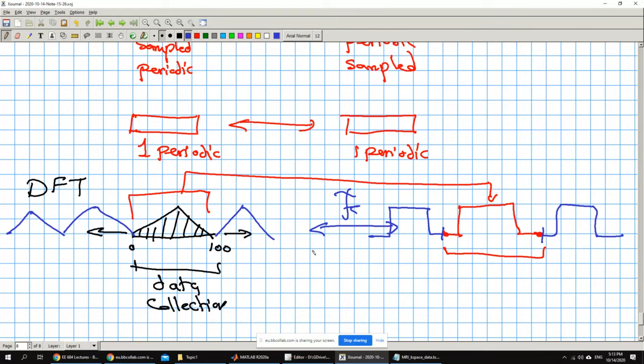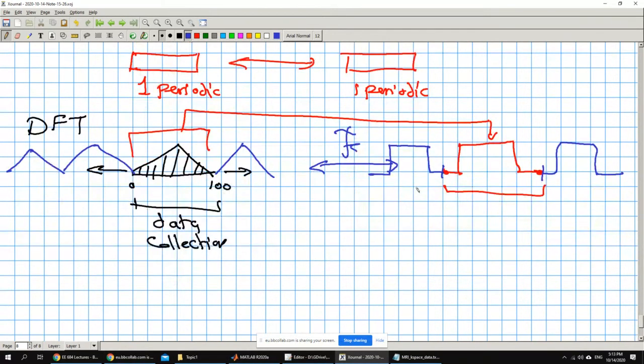If I compute the Fourier transformation of any signal, you will see only one period of the signal in time, and what comes out in the frequency domain will be another period of the frequency domain of this particular function. When I do something wrong, I will see the periodic extensions. I will show you some examples. We have to do some practical work here so that we can understand it. Without the practical examples, we will never be able to do that.